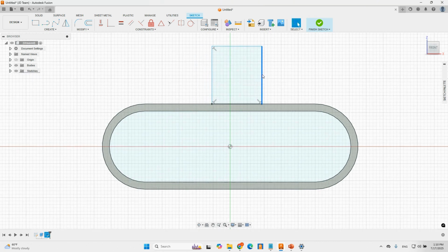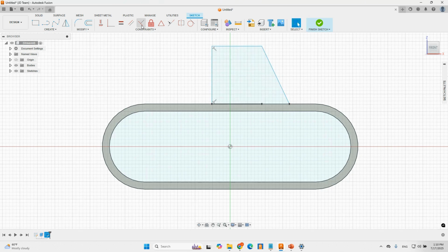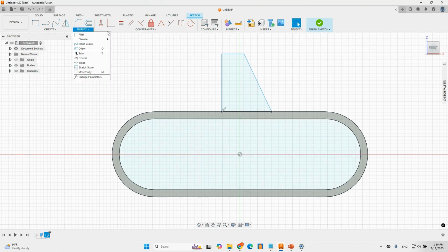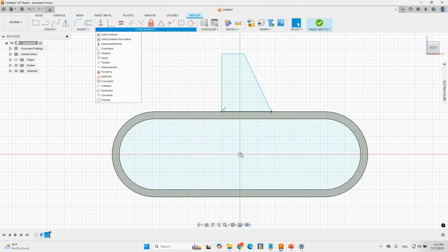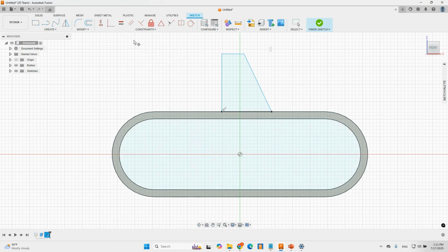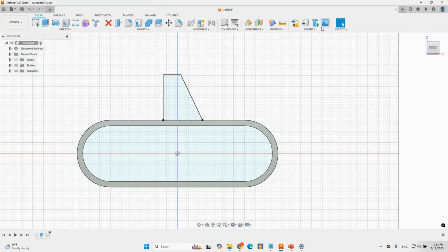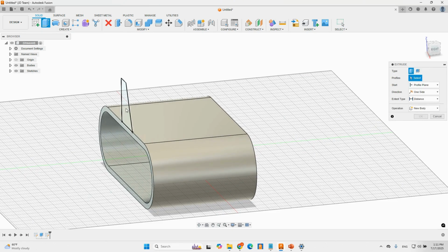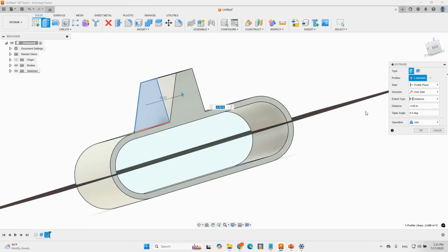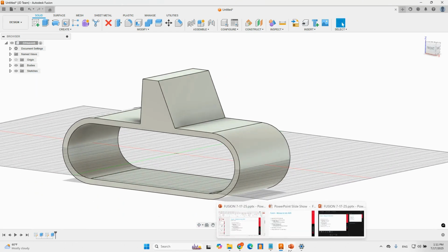All right. Maybe I can make it like this, for example. All right. Probably I don't have the constraint, right? And in a general sense, the auto constraint tool will try to reference everything towards the origin of the sketch, right? Whereas if I'm going to start my auto constraint with a datum, I'm going to specify my origin point in a certain location, and the artificial intelligence is going to define all the constraints and dimensions from that point. All right.